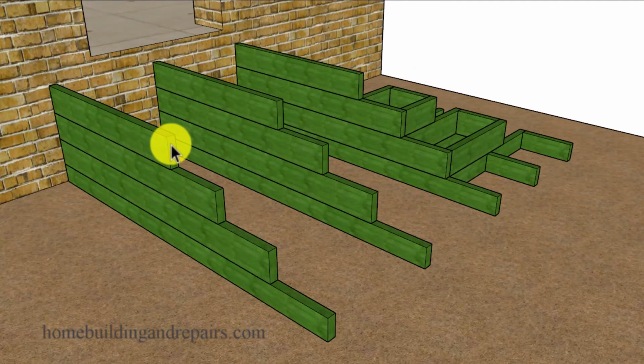However, with this design, we might have a problem with the building code that requires a 4-inch sphere or a round ball to not be allowed to travel through any part of the stairway. And we're going to be at 4 inches here. If I have a 2x6 and then I put an 1.5 inch thick decking board on top of that, I'm going to be right at 4 inches. And if I use 2x8 for something like this, I'm going to be over 4 inches.